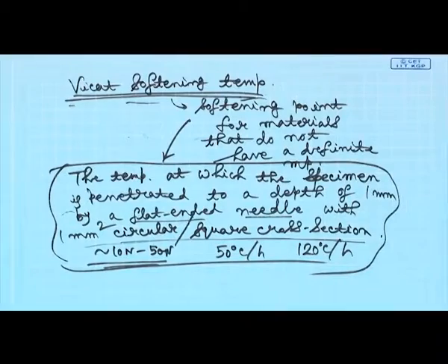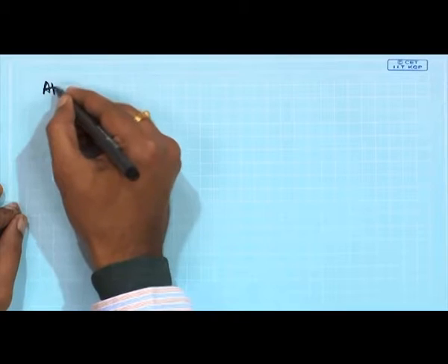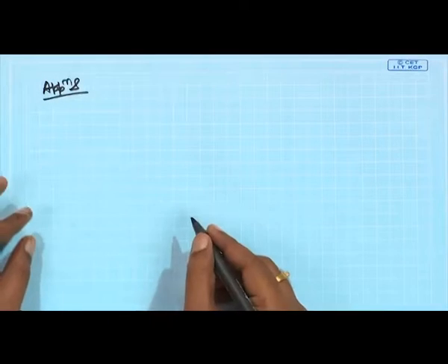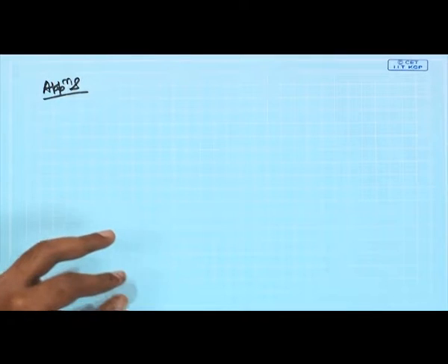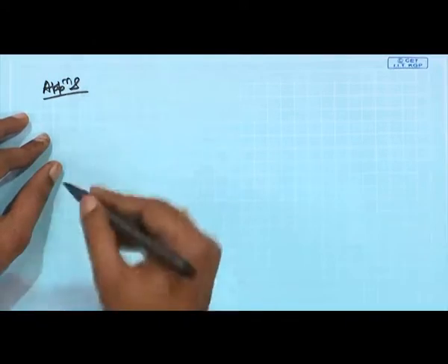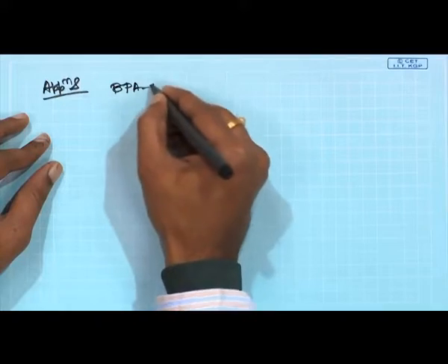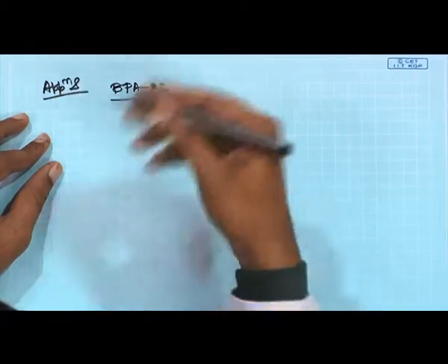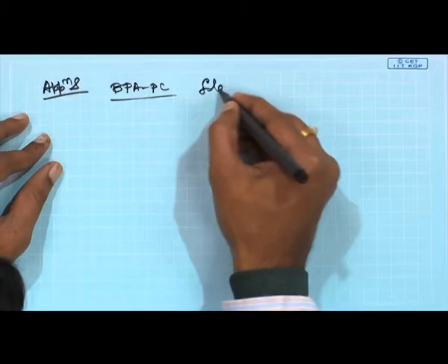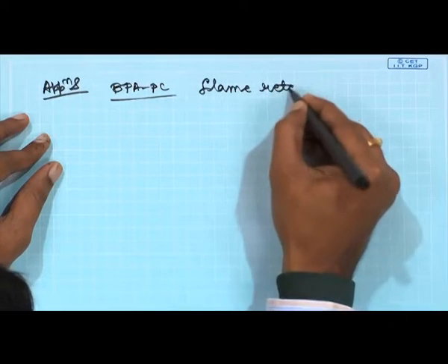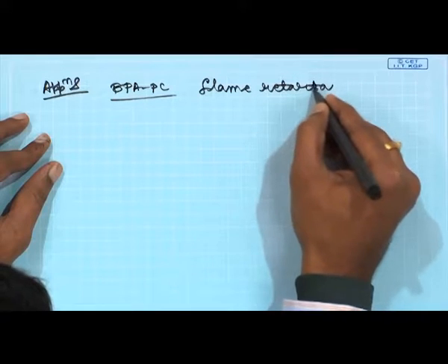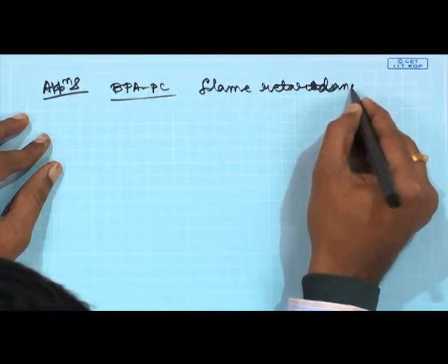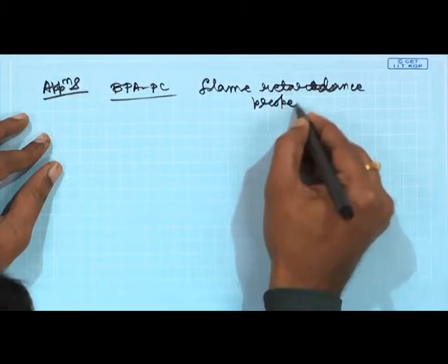Okay. So, basically then the applications of these materials: already you now understand the structure property relations, the intricate details of that, why you need aromatic units, why you need certain substitutions at one position and not in another position, and so on and so forth. So, typically BPA, bisphenol A polycarbonates, have outstanding electrical insulation, good flame retardance property, and high heat resistance.